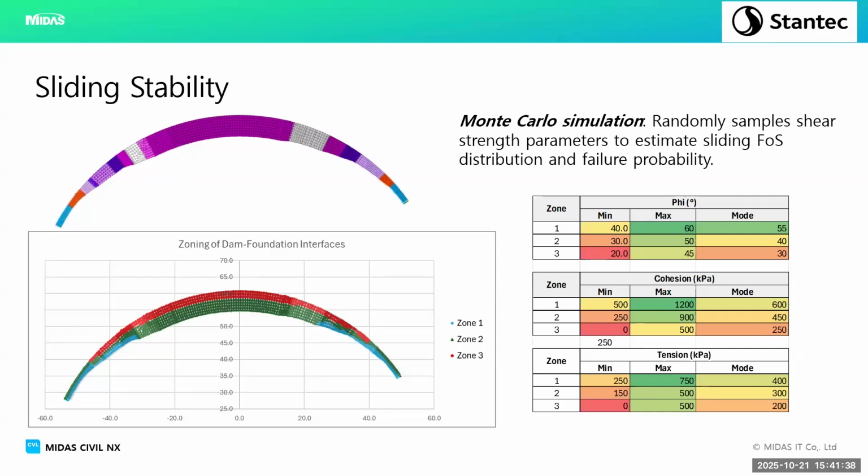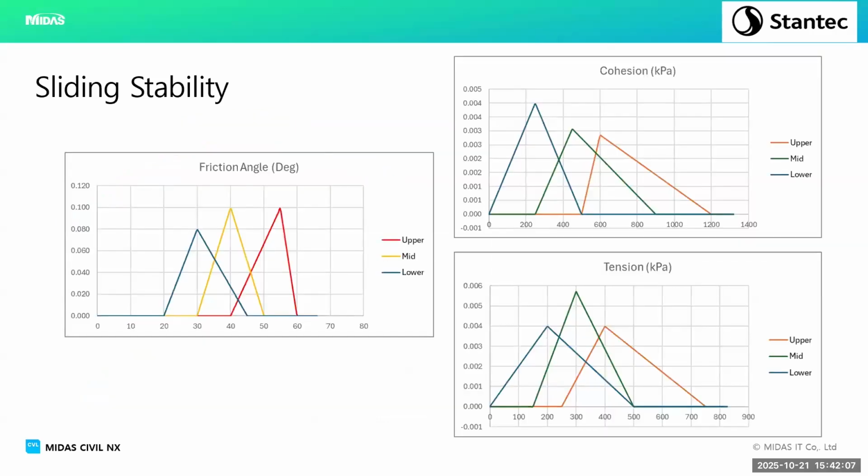So we have our results extracted from MIDAS. We've chosen our distributions. We've got our material parameters, or material strengths, that I just went through, and you can see the parameters there. We calculate the sliding factor of safety for each as we go in iterations. I think we've got pretty good convergence at about 5,000 samples, which wasn't too bad. These are just the distributions.